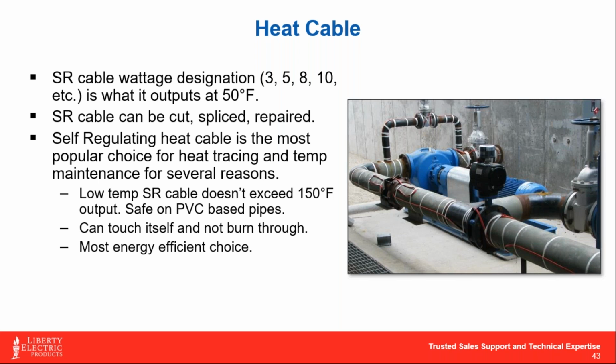But it is important to note that in cases where you're using something like PVC piping, because it's maybe just wastewater, you've got to be careful not to put too much heat on that PVC. Now, granted, the cable itself, like a low temp self-reg cable, will only work to a maximum of about 150 F. Oftentimes, if we double this up a little bit too much, it can be too much heat for the pipe, and over time, it can disfigure it. And we just don't want that type of thing to happen. So, let's dial it in with the correct information up front. And if it requires special application where we have to use a more robust cable, there's MI cables and constant watt cables that can take higher temperature exposure better than some self-regulating cables can.